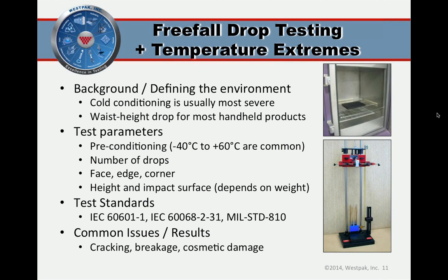All right, thank you, Herb. So next we're going to talk about freefall drop testing. This is dropping your laptop or your cell phone or what have you, hopefully by accident, from waist or higher drop height. Sometimes this is called impact testing, but for the sake of our conversation, we call it freefall drop testing. Typically this is done, just for the sake of convenience, at room temperature.